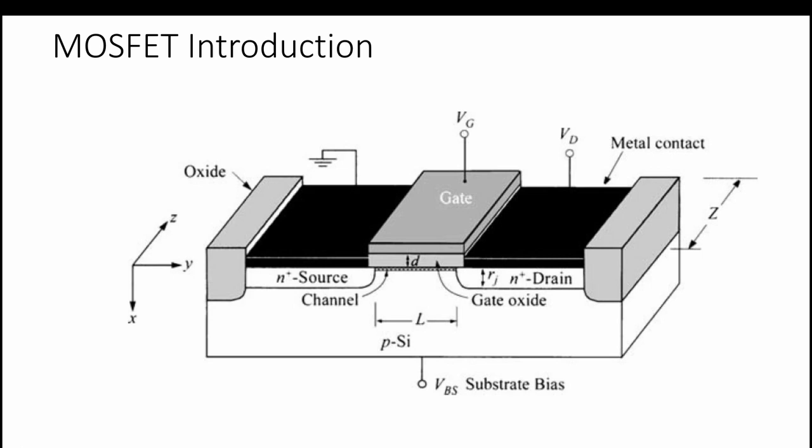What we have discussed recently was the MOSFET. This is the gate, and this is the dielectric. This whole part is the MOS structure, and this is the p-type semiconductor, p silicon. When we apply a positive bias here, there will be creation of an inversion layer at this interface, a very thin layer of electrons. This we call the channel.